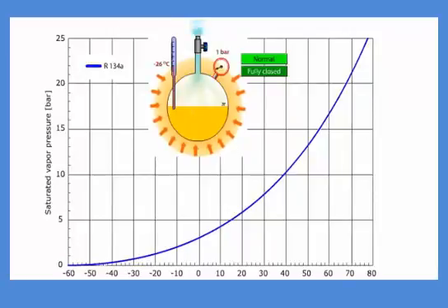You can see that the saturation pressure depends on the temperature of the mixture. The higher the temperature, the higher the saturation pressure. The saturation pressure is a unique property of the substance. The different refrigerants do not have the same saturation pressure temperature dependency.